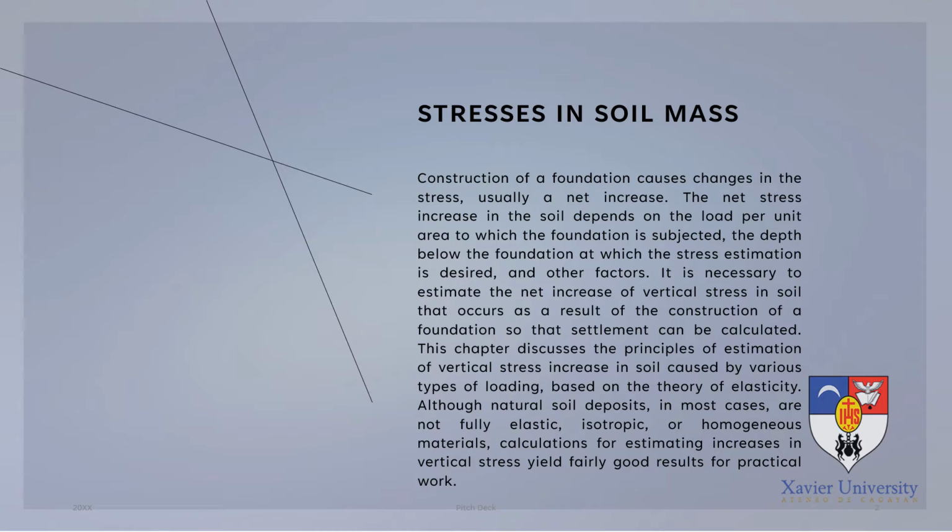The net stress increase in the soil depends on the load per unit area to which the foundation is subjected, the depth below the foundation at which the stress estimation is desired, and other factors. It is necessary to estimate the net increase of vertical stress in soil that occurs as a result of the construction of a foundation so that settlement can be calculated.